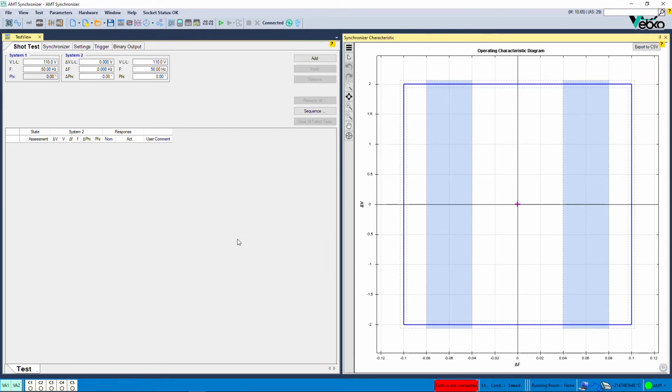used and uses the voltage of both sides to examine the state of frequency and voltage, and if the difference between the generator voltage range and frequency and the grid is less than the specified limit, the connect command is issued. If the mentioned difference is more than the specified limit, the relay will not issue the command for the connection. In this case, the relay examines the generator frequency and voltage state compared to the grid.